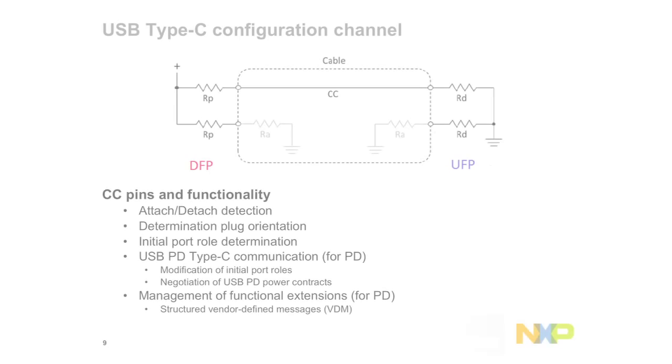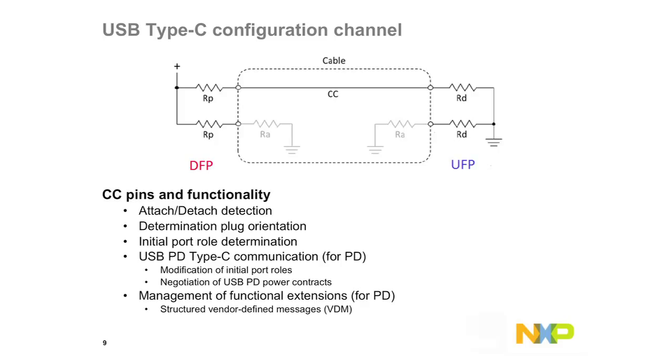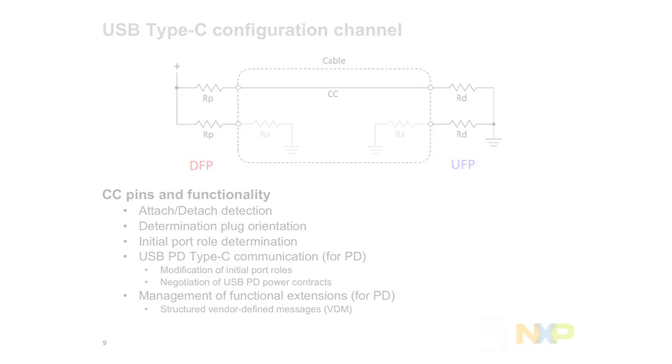Also, when you support power delivery and alternate modes, the same channel is used for sending modulated messages on each side, because it is scalable power charging. To put it in a picture, imagine my notebook having a USB Type-C port supporting power delivery, and a tablet that also supports power delivery over Type-C. When they plug into each other, say the notebook becomes RP and decides it is going to be the power provider. The tablet says I'm going to be the power receiver, but now it's scalable.